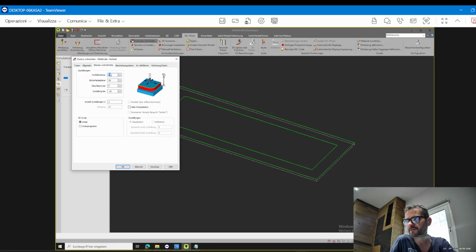What we choose is the third menu, where remember we just have to set the millimeters that you want to go down in the piece. For example, if it's 1 centimeter inside, you just press -10. And it's enough. You press OK.